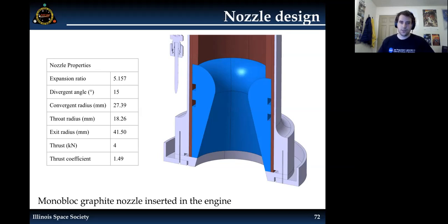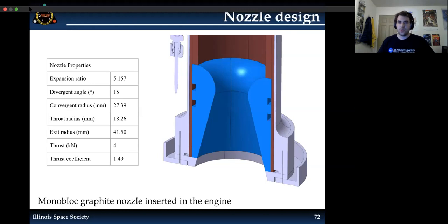This also shows, so this here, the blue is your nozzle, and then you have the combustion chamber body, which is right here. This piece here is called the retaining ring, which I'm going to talk about in a second. The red here is the thermal protection system, which we've previously talked about, which protects the aluminum body from the hot combustion gases. And then these 2 holes here are called O-ring grooves. So they're grooves that contain O-rings, and we're going to go into that later today.